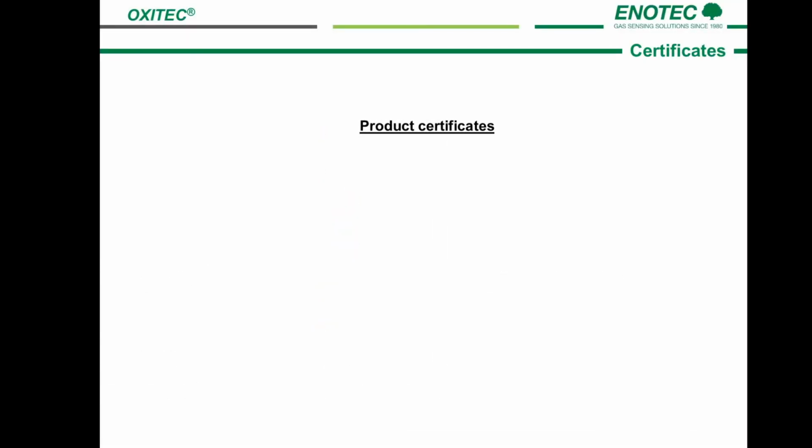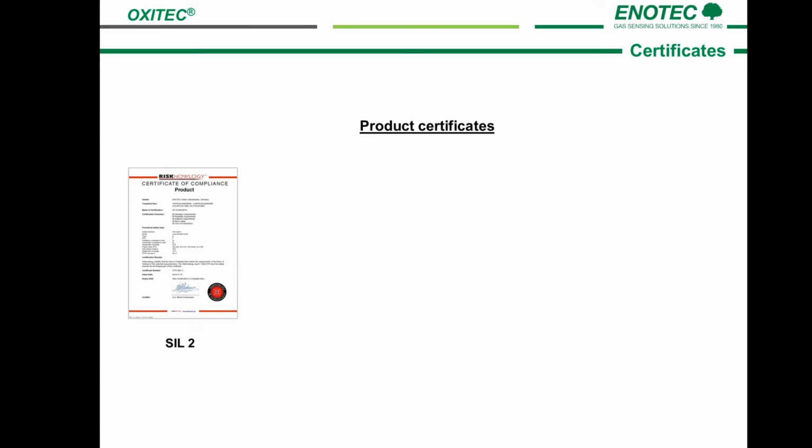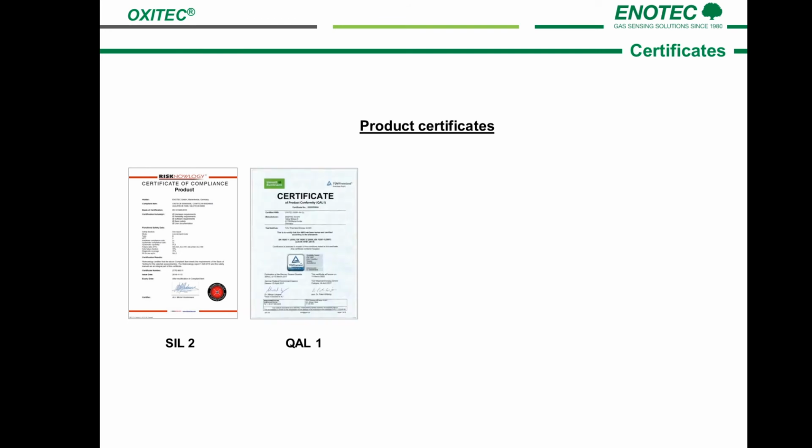That the ENOTEC analyzers measure correctly over a long lifespan is not only my opinion. We have many certificates to illustrate this. Firstly, we have the SEAL 2 certificate with a 1 out of 1 selection, meaning only one analyzer is required to reach SEAL 2. Secondly, OXITEC 5000 is suitability tested according to EN 15267 and is QAL 1 certified. The QAL 1 certificate allows a maintenance interval of 6 months, longer than any QAL 1 tested analyzer.